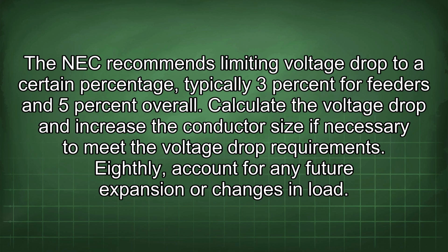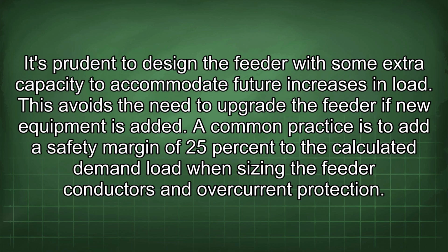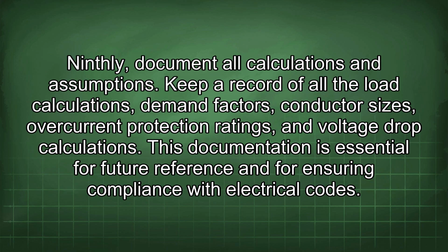Eighthly, account for any future expansion or changes in load. It's prudent to design the feeder with some extra capacity to accommodate future increases in load. This avoids the need to upgrade the feeder if new equipment is added. A common practice is to add a safety margin of 25% to the calculated demand load when sizing the feeder conductors and overcurrent protection. Ninthly, document all calculations and assumptions.